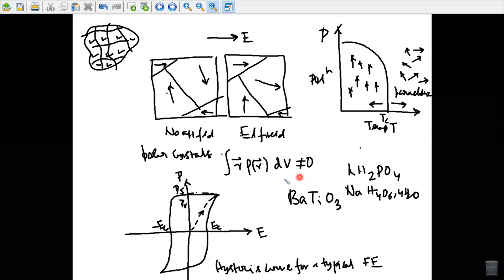The pyroelectric crystals have a polarization that changes with temperature. All polar crystals are pyroelectric, but not all polar crystals are ferroelectric. Ferroelectric crystals are polar crystals whose polarization can be reversed by an applied field. All ferroelectric crystals are also piezoelectric, in which stress changes the polarization. Piezoelectric crystals are suited for making electromechanical transducers with a variety of applications.